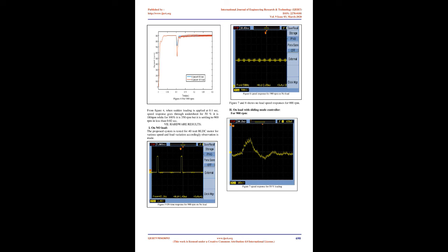4. Control method. Fig 2 represents the block diagram of the FUZZY-based speed controller. A 12V power supply is given to the motor through SMPS. The current sensor senses any change in current and gives an equivalent voltage at its output, which is then given to the controller. The drive circuit contains inverter drive circuitry which is used to change the voltage across the motor based on application. The BLDC motor is fed from the inverter and the PWM pulses are given to the inverter through the controller, and hence the voltage across the BLDC motor changes according to the control action taken by the controller. Speed of the motor is sensed by using an IR sensor. A. SMC algorithm. B. FUZZY-SMC algorithm.